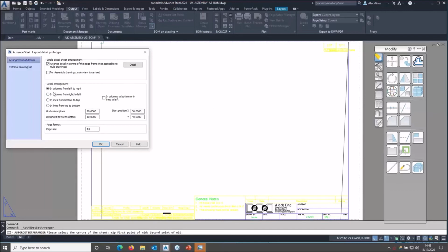Then in here, if you're doing multi-sheets, not a lot of us use multi-sheets, but if you like multi-sheets where you've got lots of parts or assemblies on one sheet, this position is measuring from the bottom left of the corner, 0, 0, to the bottom left of the first view. So if you had a big value, you might put the view over here. And then you're telling it whether to go in columns or rows. So it either goes 1, 2, 3, or 1, 2, 3, whether it's going top down or left to right. So you combine these two to decide which layout it goes in to fill up the sheet.